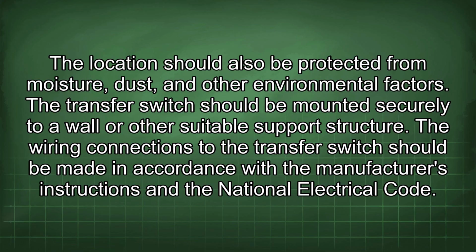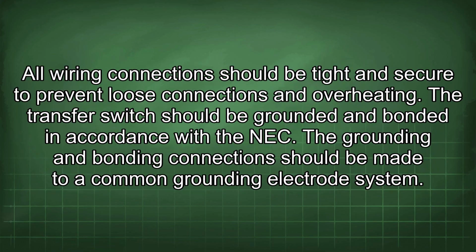The wiring connections to the transfer switch should be made in accordance with the manufacturer's instructions and the National Electrical Code. All wiring connections should be tight and secure to prevent loose connections and overheating. The transfer switch should be grounded and bonded in accordance with the NEC. The grounding and bonding connections should be made to a common grounding electrode system.